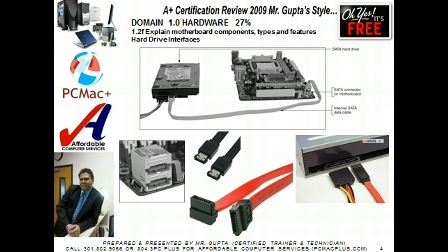Serial ATA interfaces are much faster than PATA interfaces and are used by all types of drives, including hard drives, CDs, DVDs, Blu-ray, and tape drives. A motherboard can have 2, 4, 6, or more SATA connectors, which are much easier to configure and use than PATA connectors. SATA supports hot swapping, also called hot plugging. With hot swapping, you can connect and disconnect a drive while the system is running.